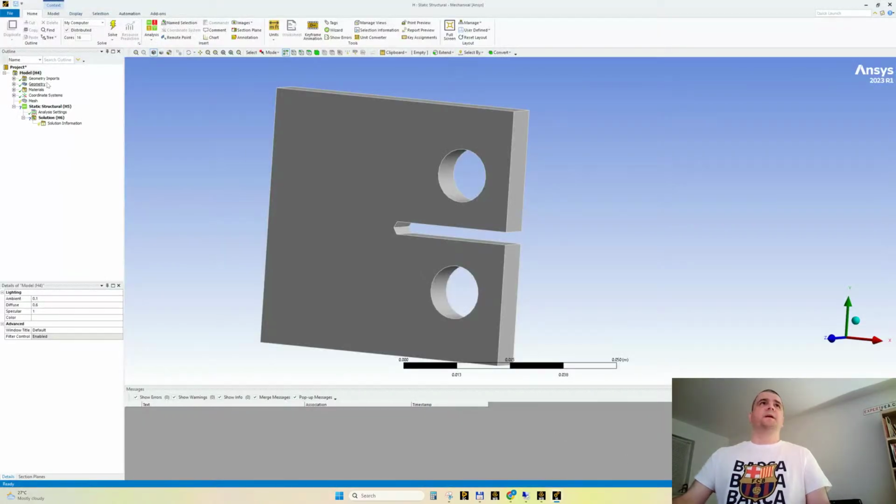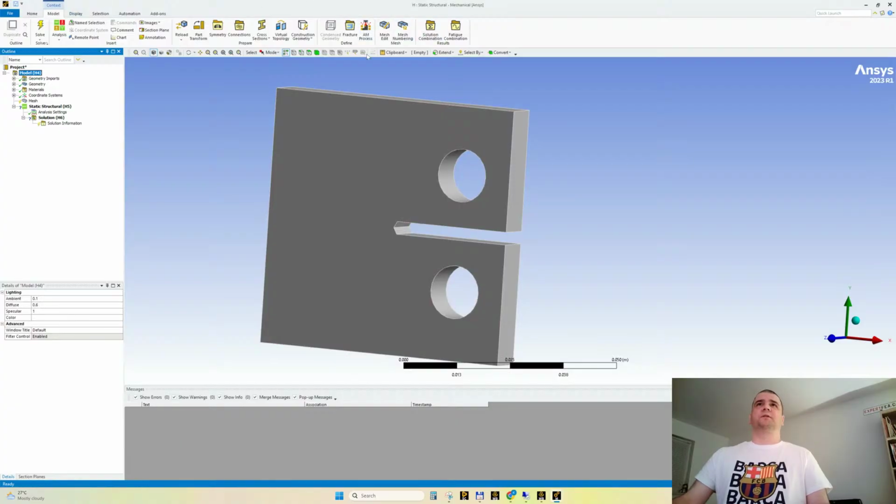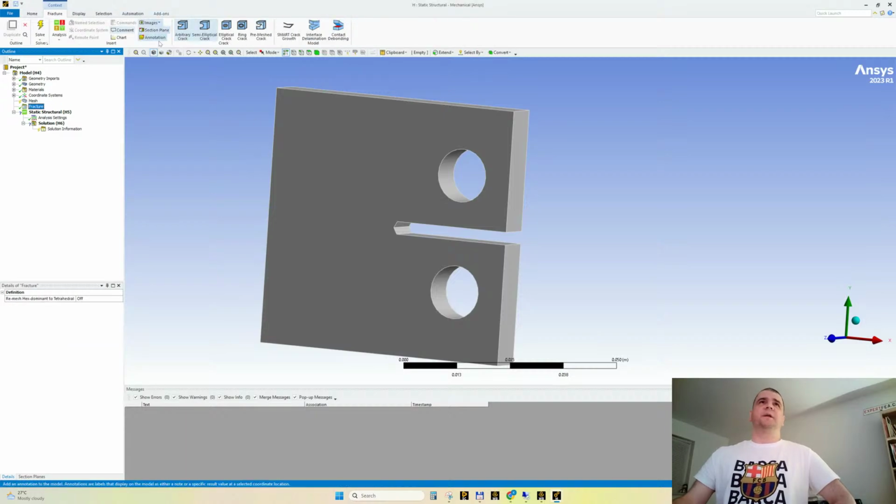Let me show you. So I was talking about the option. This is the option. In order to start fracture mechanics, we click here, and it says insert a fracture folder object, different types of cracks, smart, delamination, debonding, whatever. Let's click here just for fun, because we can see what types of cracks we can have. Arbitrary, semi-elliptical, elliptical, ring crack. These are kind of standard, and they do not allow a nice fracture.